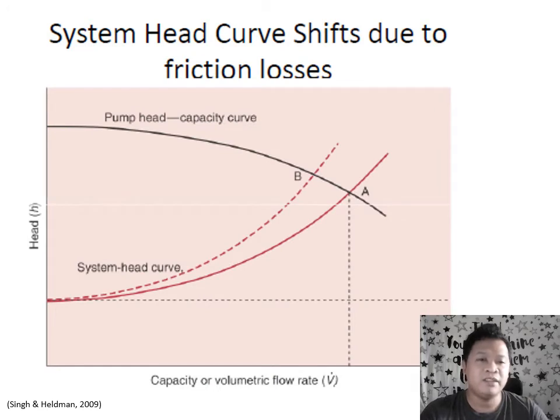So in general, anything that would contribute a friction loss in the system would shift the curve towards the left. And of course, we know that kapag towards the left yung shift niya, mas mababa yung magagamit nating maximum flow rate, no? So that's what's important, no? Kasi ang titignan lang natin is in terms of yung intersection ng system head curve at pump head curve, you want it as far right as possible, di ba? And kung mag-shift siya to the left, that means marirestrict yung use natin.